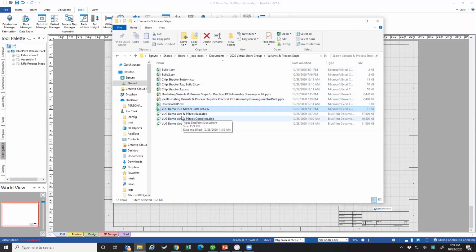But basically, I can have a master parts list, and depending on what term you want to use for uninstalled, DNI, uninstalled, DNP, you'll have columns in your parts list which identify what parts are installed and what parts are uninstalled. And the only thing that has to be entered there are when a part is uninstalled. That's the key word.